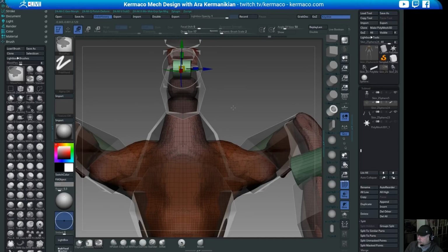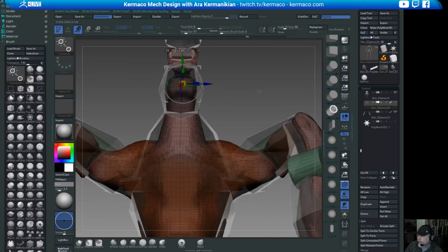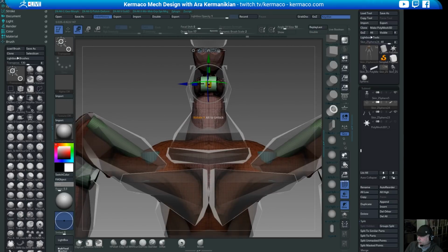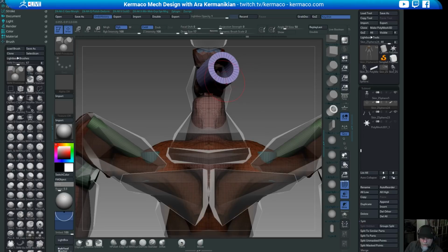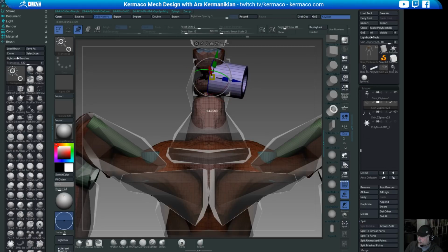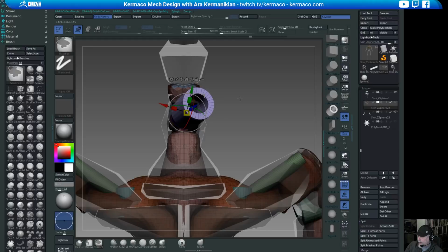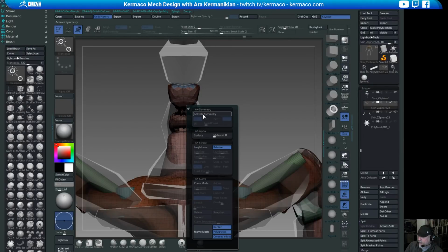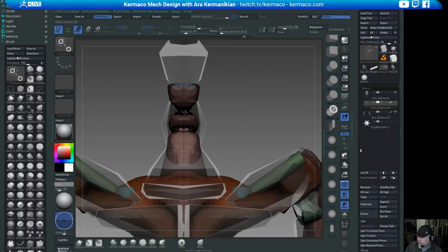So let's just start this whole thing over with perspective off. Right, so I'm in draw mode, draw this, W, rotate it. Actually, start with symmetry on, draw it out so it's exactly in the center, and then turn symmetry off and then rotate it.